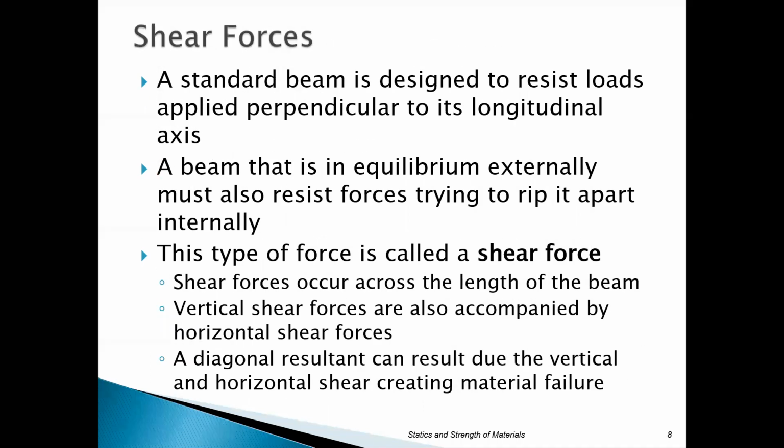So a standard beam is designed to resist loads that are primarily going to be applied perpendicular to its longitudinal axis. So again, we're pretty much going to be working in the Y direction almost always, but that's not totally true, obviously. So you're going to have other things. But a beam that's going to be in equilibrium externally must also resist forces that are trying to rip it apart internally. And so this ripping type of force is referred to as a shear force. You know, just think about like bolts being sheared, which we talked about across the shear plane. Internally, what we're saying is that beam is trying to be ripped apart.